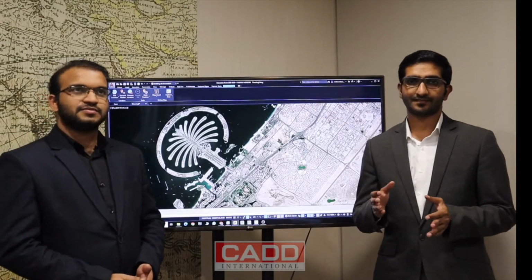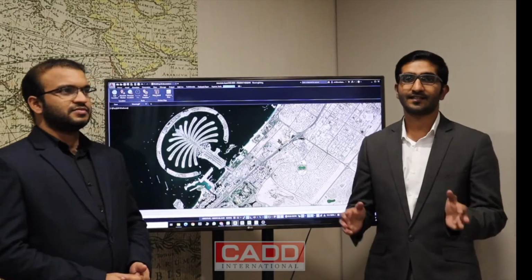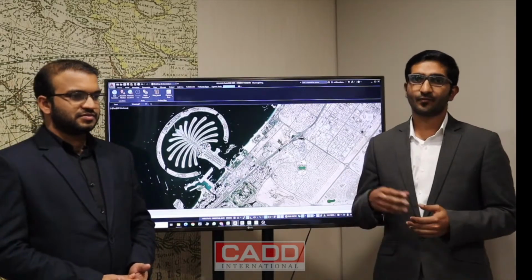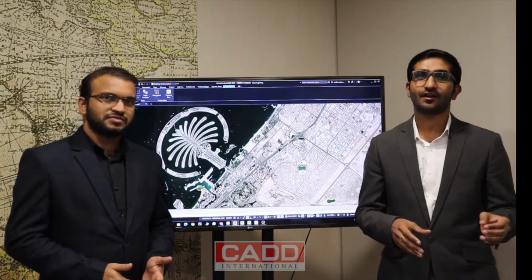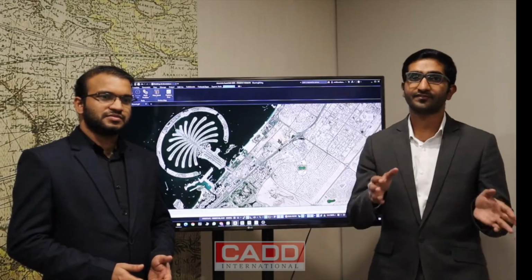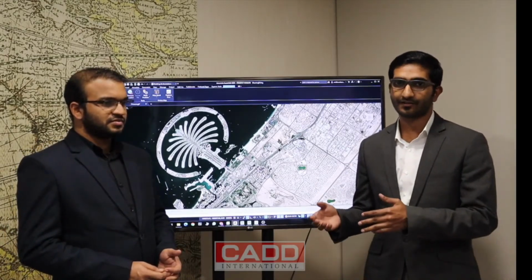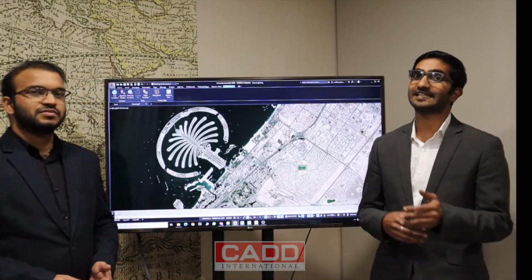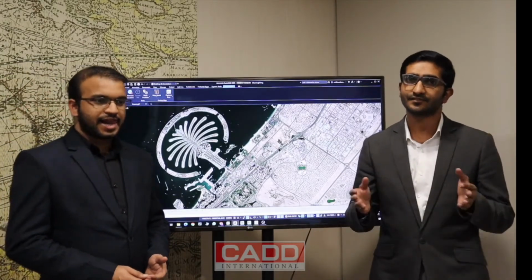So what is World Coordinate System or WCS? In WCS, the positioning of all the objects in standard views of AutoCAD is based on the World Coordinate System, which means the user cannot manipulate the position or the orientation of the World Coordinate System, and it cannot be rotated or changed. It is permanent and also it is invisible.